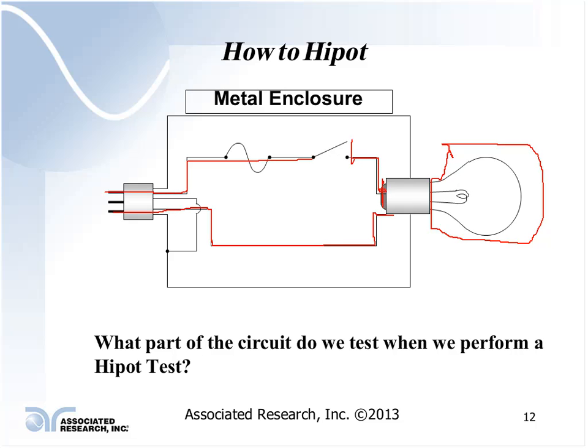Again, this is our ground circuit, and that is tied to the enclosure of the product here. So that whole circuit is basically tied back essentially to earth ground during normal operation.